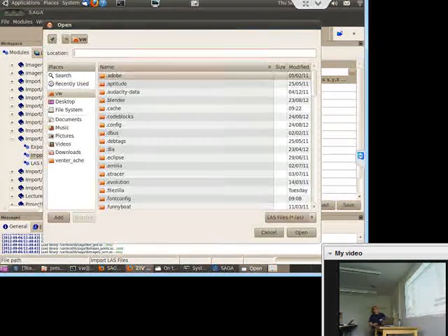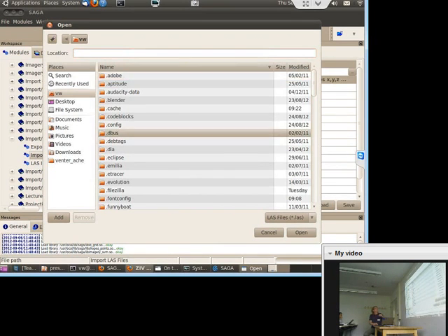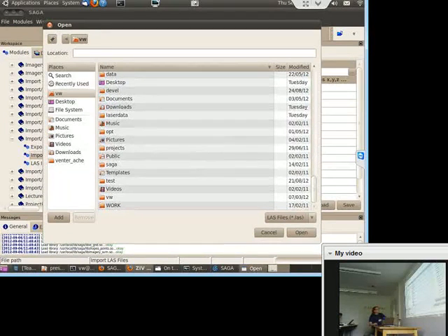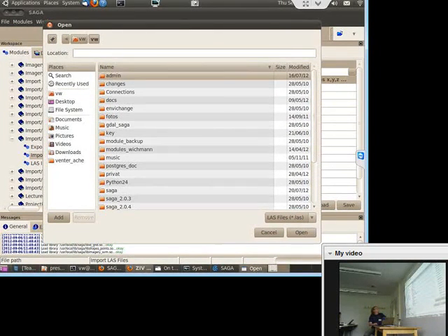The other thing, I forgot. We have forgotten to import the return number. In case you like to view it, you have to re-import it. I forgot to set the flag for the return number, which would allow you to see that we have first returns on top of the trees and higher return numbers down to the ground. But that would be just another possibility to visualize things.